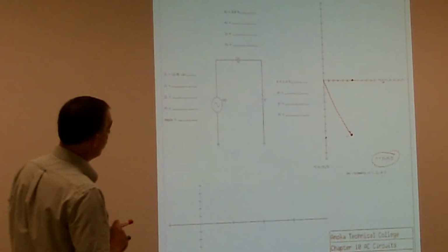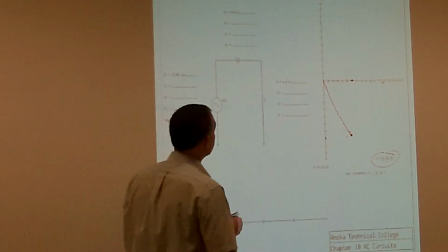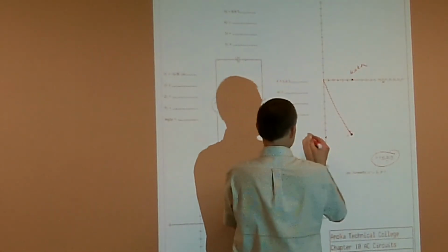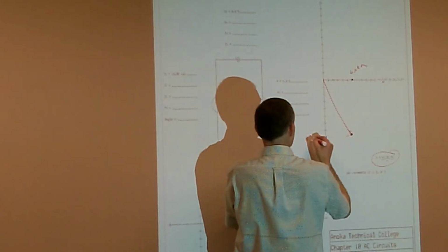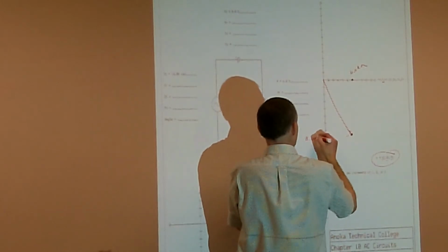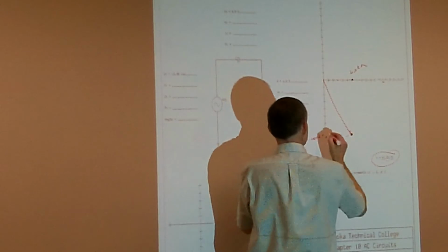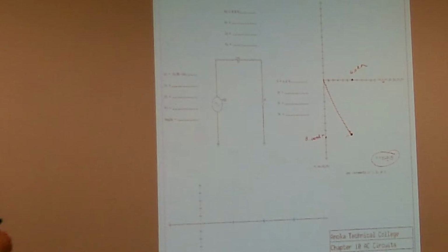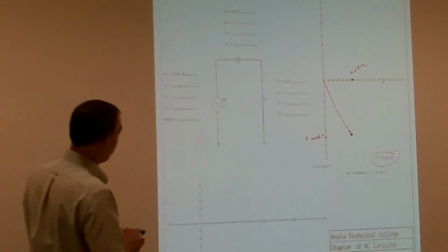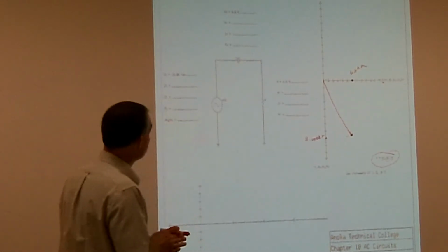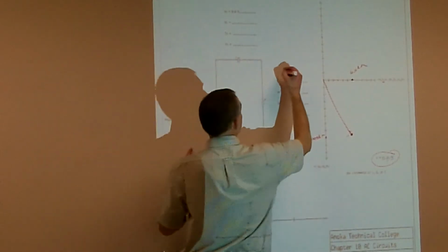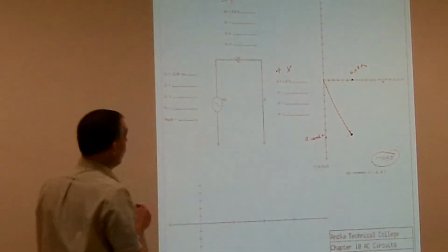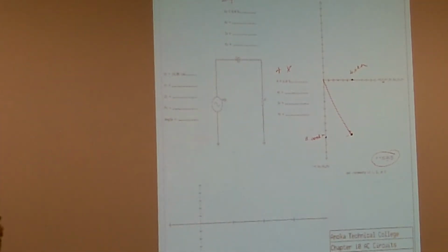All right, then what's my next step? Find the ZT. If we know two things, we can always find the third. Just the same thing when we're doing trig. Once we know two, we can find the third. So what do I get for ZT then? Make sure you remember that this is plus X and this is negative Y. So when we're entering in the calculator, we have to make sure we put in our polarities.